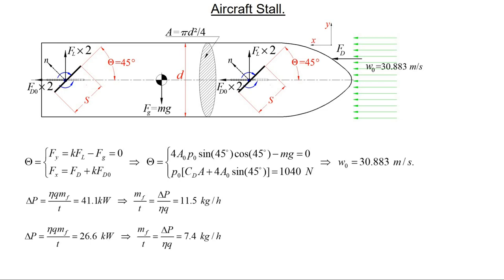From the perspective of math, it is a function to solve the physics problem of lift when we have 6 parameters. Every time we change some parameter, for example, the surface area of the wing, it also increases the mass of the total airplane. In civil aviation, for wide-body fuselage airplanes, wing plays a role as the extra fuel tanks. For people who are interested in multi-complex physics problems, it's an interesting mathematical problem with many parameters and 2D variables involved.